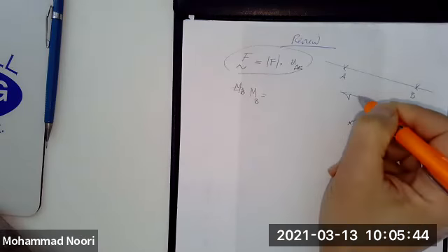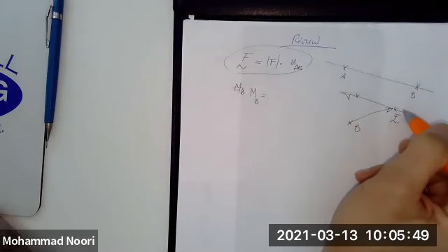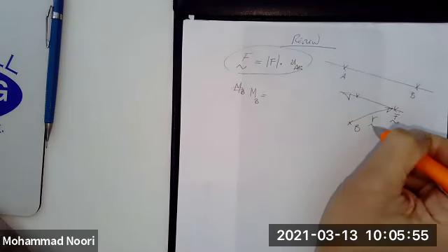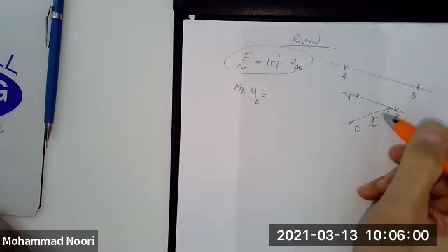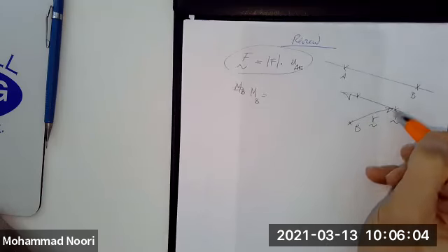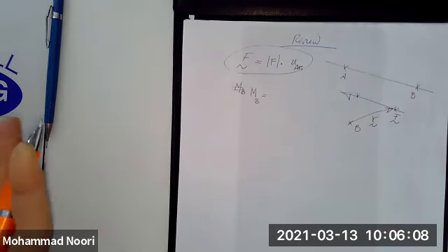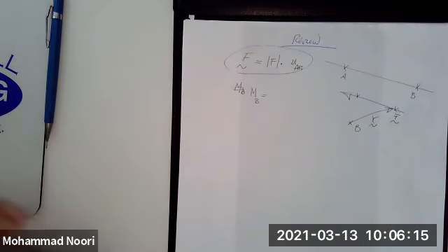Of course, typically you're given no more than 2 points along that direction of the force. So you choose one of those, and preferably the easiest one, so that this position vector that results would be easy. In other words, if the coordinates are such that you can connect this to a point along the force, and that position vector, for instance, gives you a vector that is along the x or along the y, obviously has only one dimension, makes your life easier.